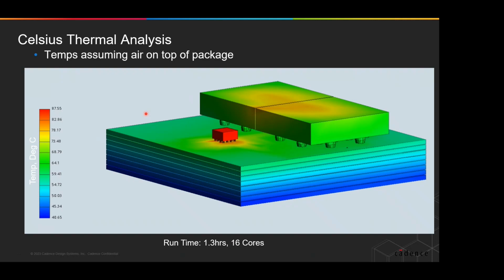Finally, we ran a thermal simulation of the entire design. So here we have our 2 power amplifiers, power amplifier A and power amplifier B, along with our regulator. You can see the regulator gets to be the hottest at 87.5 degrees, with the power amplifiers nominally following along. The baseband chiplet is on the bottom, but its power dissipation, being that it's in CMOS, is negligible compared to the heat generated by the regulator and the power amplifier.